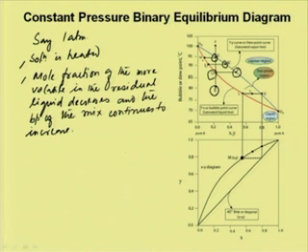When all the liquid is vaporized, the vapor must have a composition equal to the initial liquid composition at E. Now, if no further heating is done, then the final state of vapor is given by point X, which is on the vertical line from E to X. If we further heat this solution, then the temperature will rise vertically along EF.